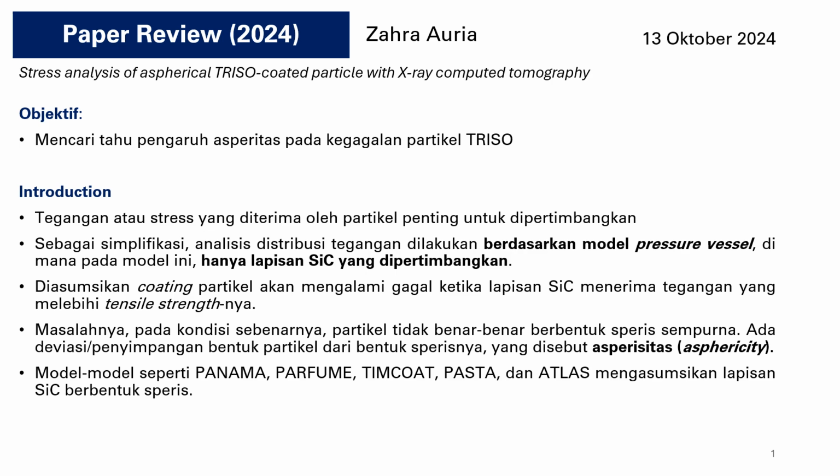We assume that the particle coating will undergo failure whenever the silicon carbide receives stress exceeding its tensile strength. The problem is that in real conditions, the shape of the particle is not really spherical. There are some deviations from the spherical shape, and we call that asphericity.